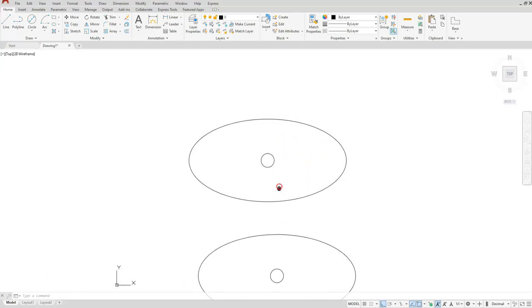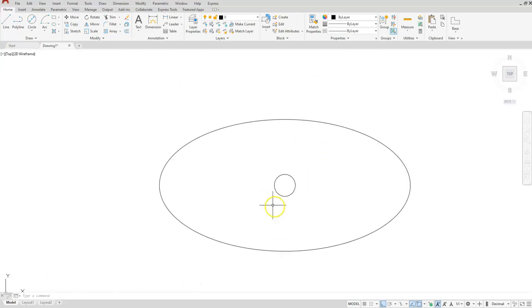Okay, so let's go ahead and create the smaller ellipse on the inside. So I'll choose the center option. I want you to touch the center of your circle here. Get out as quickly as you can. Try to avoid the quadrants. Once I have my tracking, I tell it the distance that I want to go. In this case it is 1. Now I can tell it how wide I want this ellipse, just 0.25. And then how tall this ellipse is, which is 0.75.